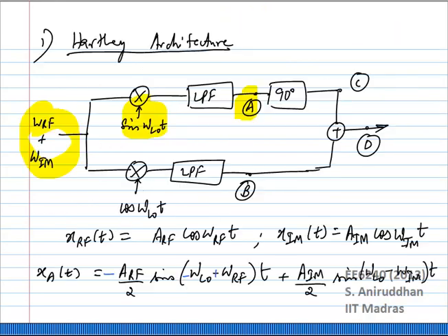So this looks very good. So the magnetic issue is also, the amplitude is also, you can only one frequency. Correct. So that is one big drawback. Obviously, the fact that the amplitude is matched only for one single frequency is a huge drawback, because any signal will actually have a finite bandwidth, and you will get cancellation at one particular frequency, but around that frequency you will get imperfect cancellation, right? Okay, so that is one problem.